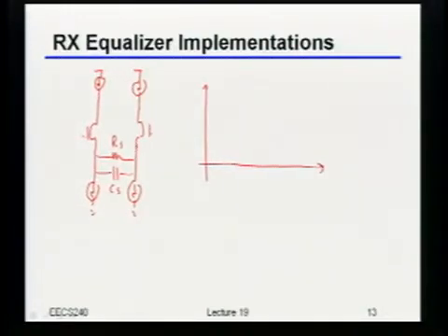Eric's got it. Okay, so basically, we'll start out with some DC gain. It'll have a zero in it, and then it'll flatten out at some peak gain again, right? Let's call this A DC and A peak over here. I'll be slightly more realistic. We'll even assume there's some output resistance from those current sources so that the peak gain isn't actually infinity.